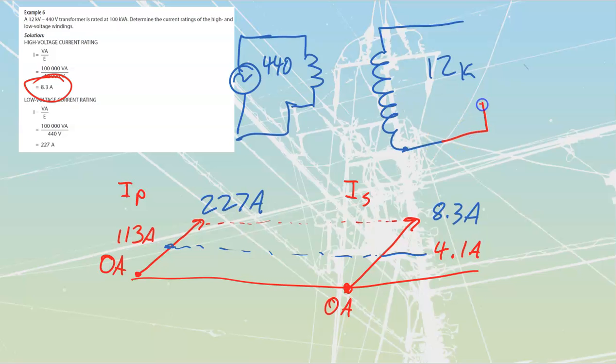If I have a really low value of resistance, we'll draw two resistors in parallel to drop our resistance here. If I was at a really low value of resistance, at my 8.3, my maximum amount of current on my secondary, I would also be at my maximum amount of current on my primary over here. Okay? Understand that this side here and this side here are related via the transformer ratio. TX is short for transformer. The transformer ratio relates them, but then we just use them to make either a smaller or a larger reflection, but they move at the same time.